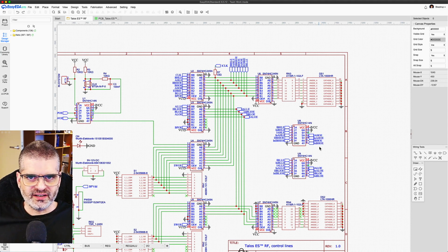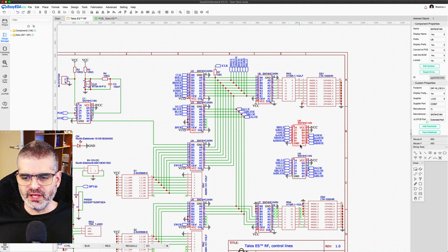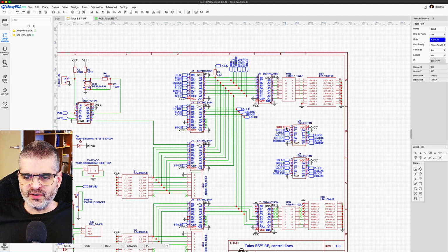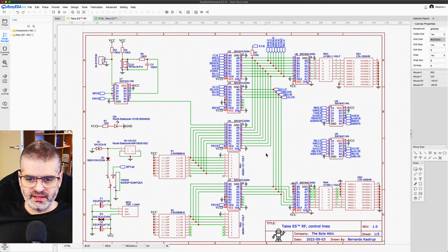The signals are active low, so we have to invert everything. So for every signal, like local B high load enable, it passes through an inverter and comes out as the local negated B high load enable. So LN instead of just L. And it's the same convention for all the other signals. And that is pretty much this chart.